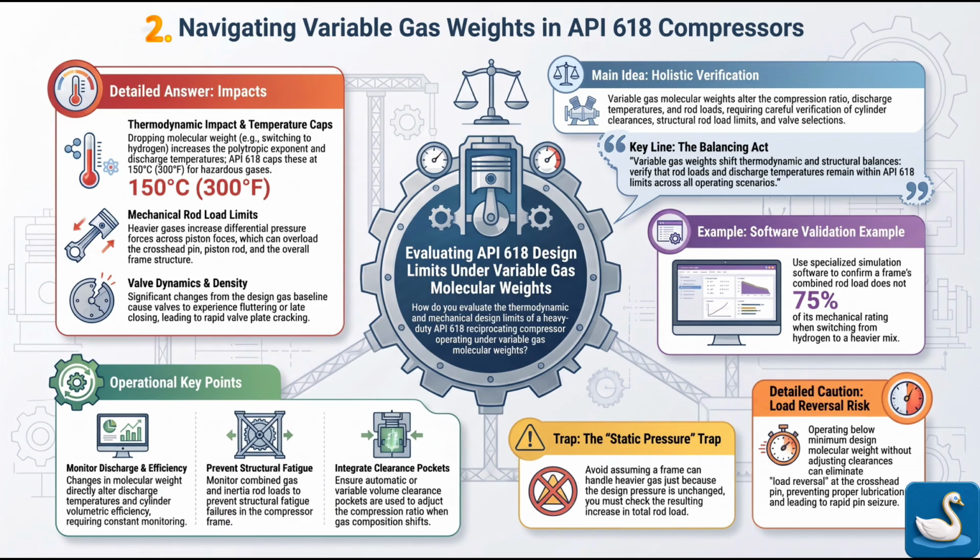Those bands are the only things keeping the steel piston from touching the steel cylinder wall. So if they melt? Once that Teflon melts or extrudes out of its groove due to extreme heat, you lose your sealing and you invite raw steel grinding against a steel cylinder liner at 1,000 cycles a minute. That sounds catastrophic. The machine will literally tear itself apart from friction before the operator can even hit the emergency stop.